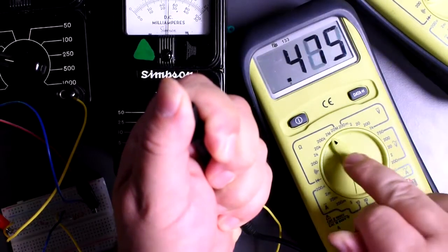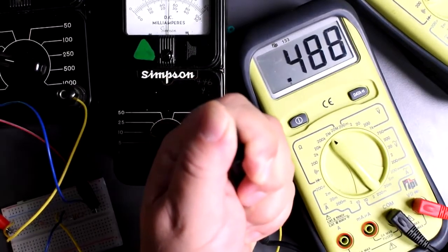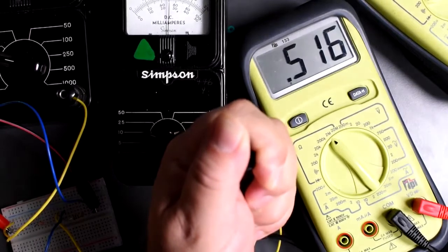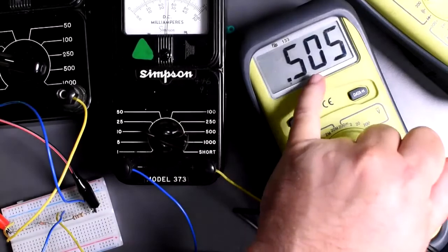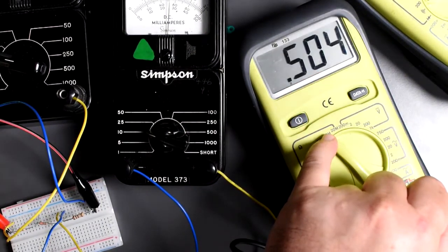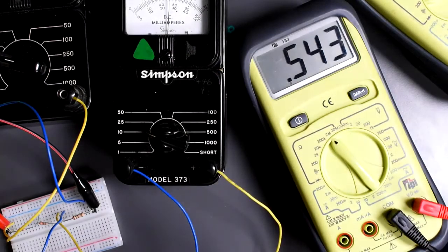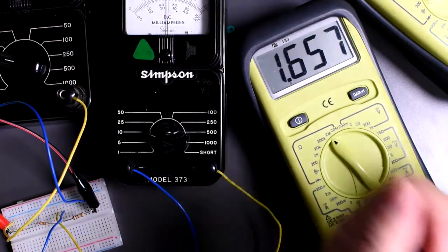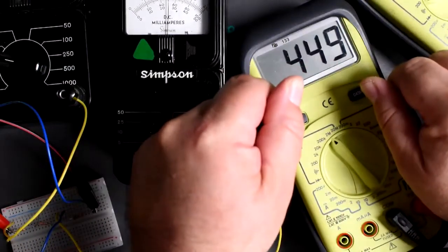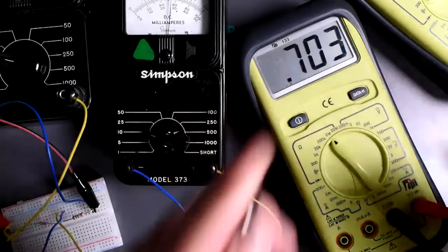So because it's 2 mega ohms, mega means times 10 to the 6th, so it's 2 million ohms. So whatever we see here on the display, we're going to have to multiply by 1 million because we're in the range of millions. So times 1 million, I got about 500,000 ohms across my hands. Okay, I'm holding those probes. About 500,000 ohms. So I do have some resistance.